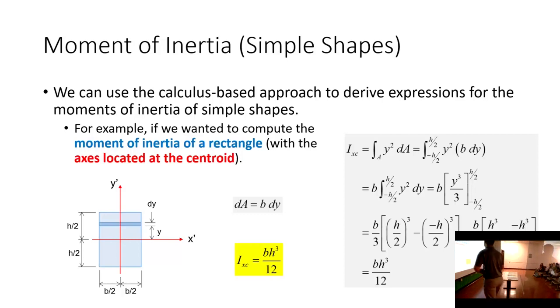So what I am computing is a moment of inertia with respect to the centroid. In fact, centroidal moments of inertia are among the most useful to us as engineers. All I'll say about that is it's an incredibly standard place about which to compute the moment of inertia, but the main reason for it has to do with deformable bodies, with deformations. Largely, what you will find is that flexural bending theory is a function of the moment of inertia being referenced from the centroid.